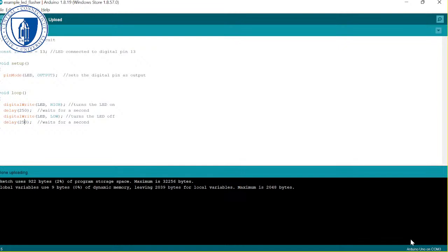I believe there are some other ones that are analog output. Yeah, they're digital. The analog is analog inputs. I think the only way you can get an analog output out of this is doing something like PWM, pulse width modulation, to synthesize a particular voltage.